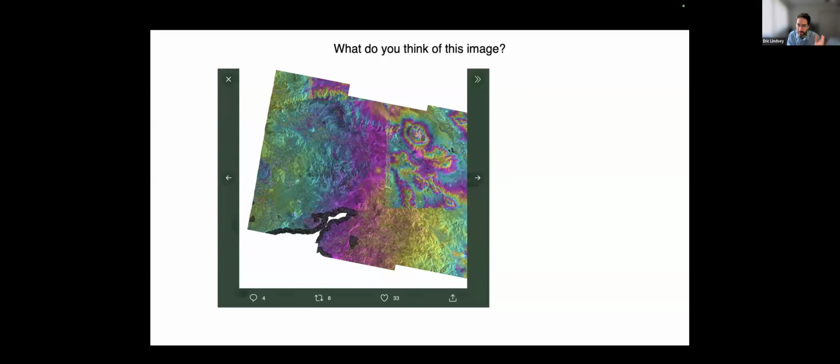This image has been geocoded, so these lines are facing exactly north, south, and east, west, right? When you download SRTM from the USGS website or NASA or wherever you download it, it usually comes in 1 degree tiles, and you have to download all those tiles and then combine them together to make your DEM.